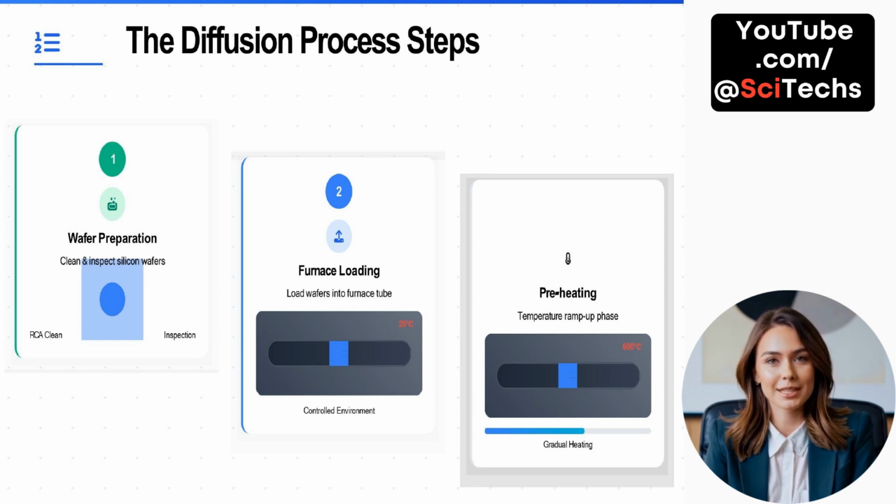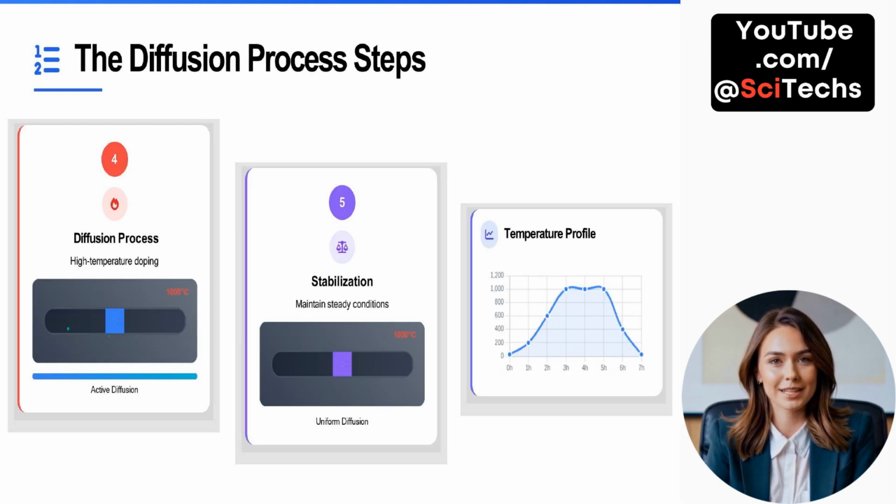Next comes preheating. This step ramps up the furnace temperature gradually to prepare the wafers for diffusion. Controlled and uniform heating, reaching approximately 600 degrees Celsius, is essential to avoid thermal shock and ensure even temperature distribution. This step transitions the wafers from room temperature to the thermal conditions required for effective dopant movement in subsequent diffusion steps.